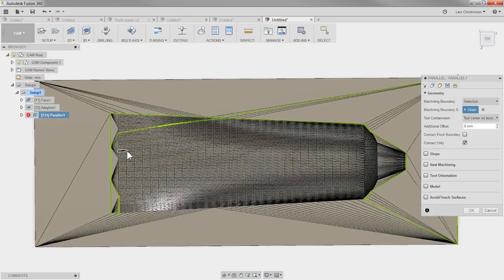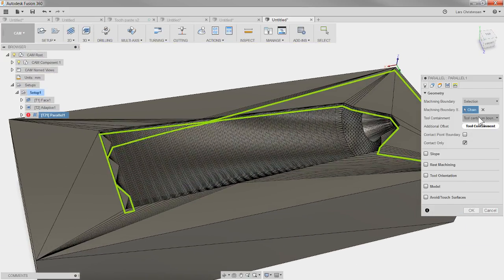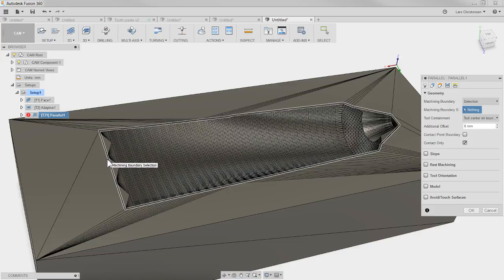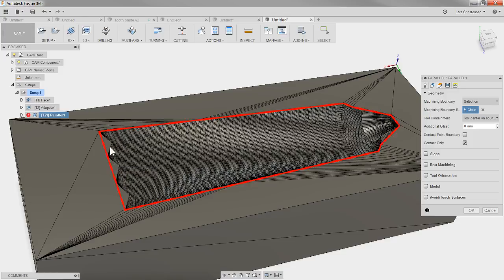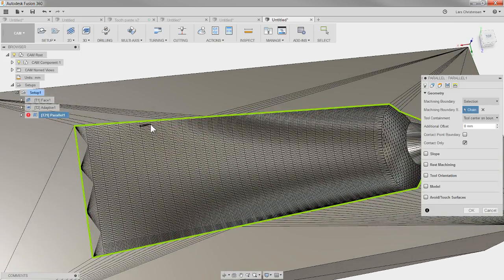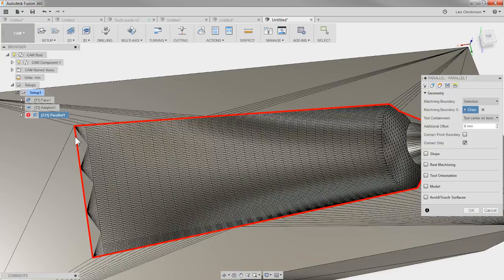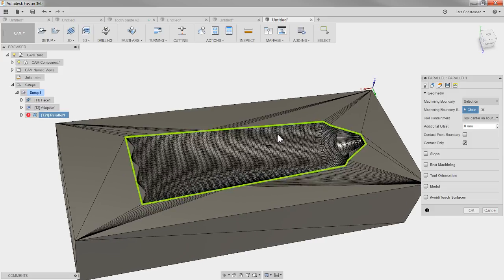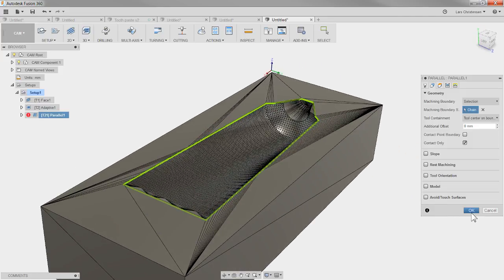And I'm actually ending up getting two green. This is actually not what I want. Ha! Well, this is actually what I want. This is the great thing about doing live streams. I want that whole area. So be aware that if it misselects, you can go in and click on the same one. Even if this is the wrong one, I got the right one, but now you can see how it's trying to figure out with all the edges what it wants. So that's what I want. I want to select this area here to be my toolpath within. I hope that didn't become too confusing.